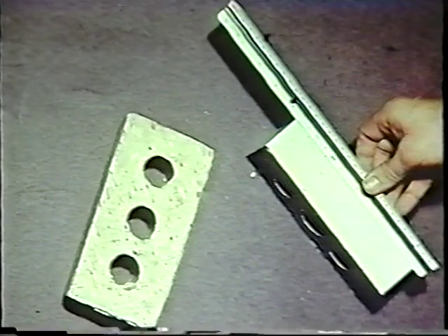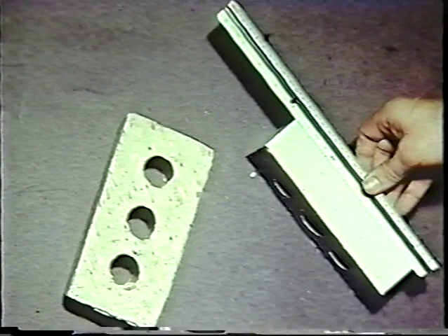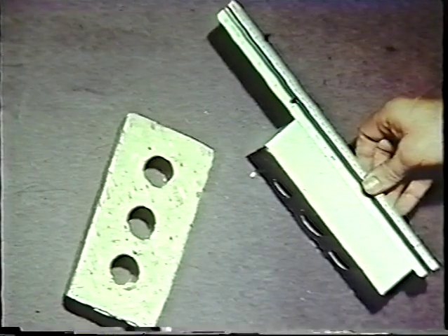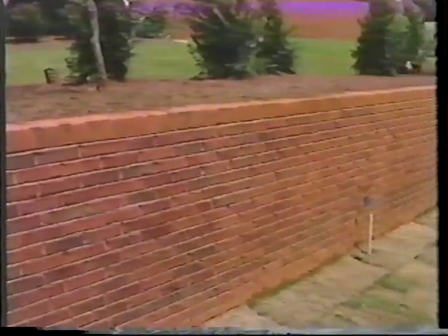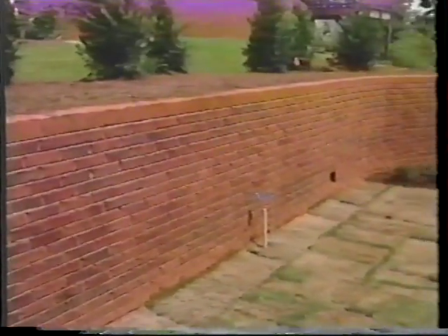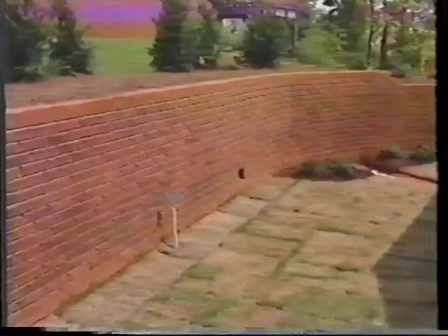Some materials expand or contract with a change in moisture. A brick is the smallest it will ever be when it comes from the brick plant. It will continue to increase in size over a prolonged time period. Most of this expansion occurs within the first few months, and then very slowly after that. The brick could expand up to 1/3 of an inch in 100 feet due to moisture expansion.